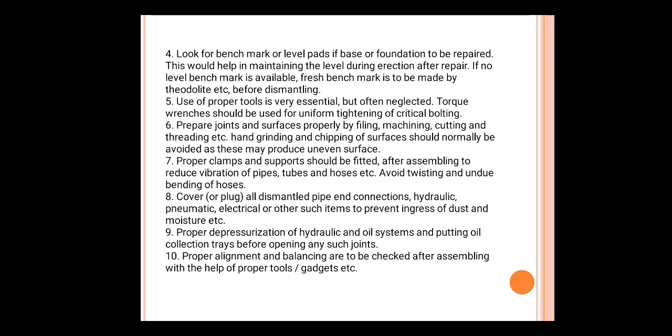Sixth, prepare the joint surfaces properly by filing, machining, cutting and threading. Hand grinding and chipping of the surfaces should normally be avoided, as these may produce uneven surfaces.